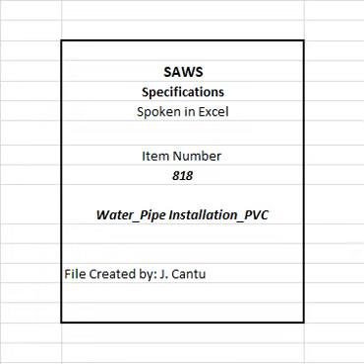818.3 Submittals. All submittals shall be in accordance with most recent version of SAWS General Conditions Requirements. Submit the following prior to performing any work. 1. Certifications. A. Per General Conditions Section 5.12.2 all contractor submittals for all pipe and other products or materials furnished under this specification shall be marked as reviewed and approved by contractor for compliance with contract documents and the reference standards. B. The manufacturer shall provide ISO 9001 certificate by a third party.